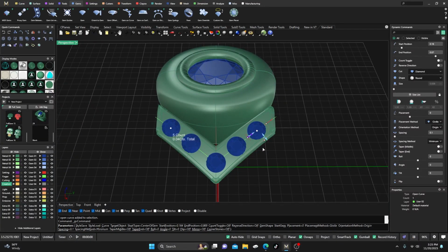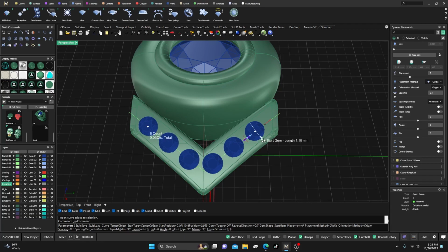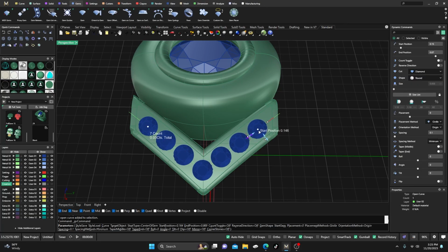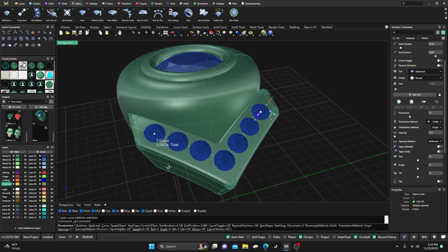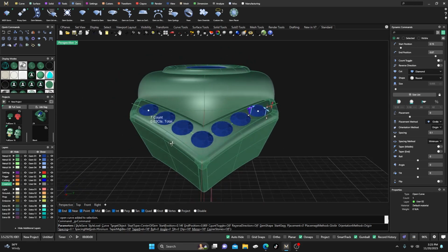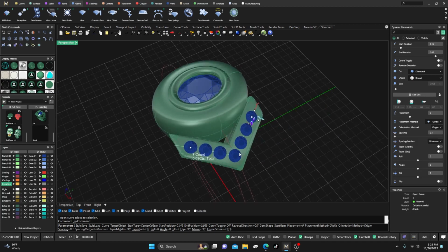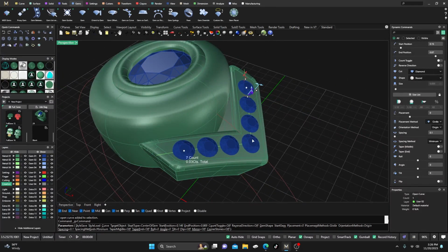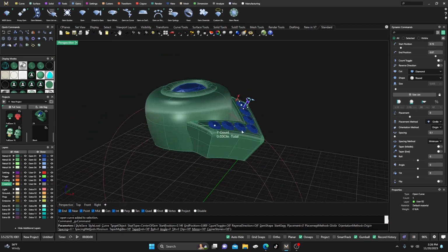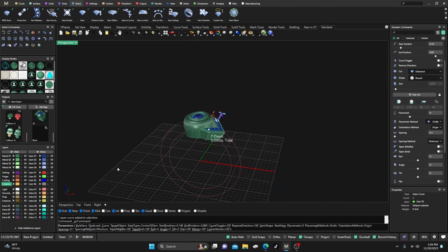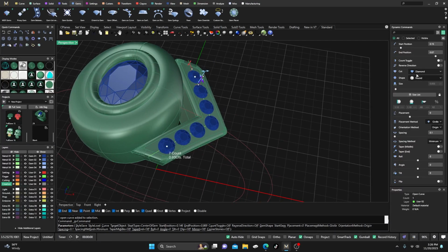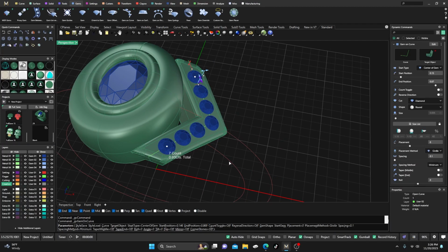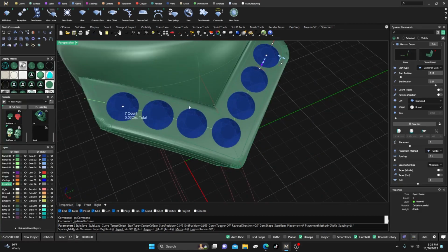Spacing's a little hinky here, huh? Well, you got 5, but probably had to make that a little bit larger to get the larger stones out there. So I apologize for that. Again, I don't know how many stones or what size gems you're looking at, but you can get it doing something like this. Just maybe have to make that a little larger. And before you do that, you could always just grab that curve and 1D it out a little bit, which would make it longer, right? So there's a lot of ways to do it. So we'll just say that's kind of what we want. We'll go ahead and target our surface to make sure everything's nice and flat there.